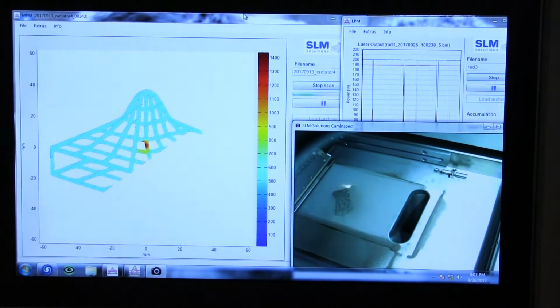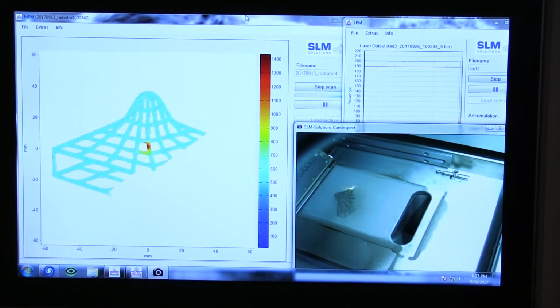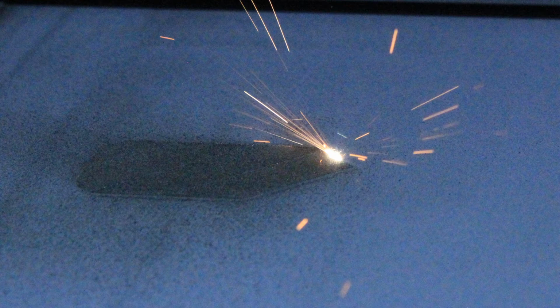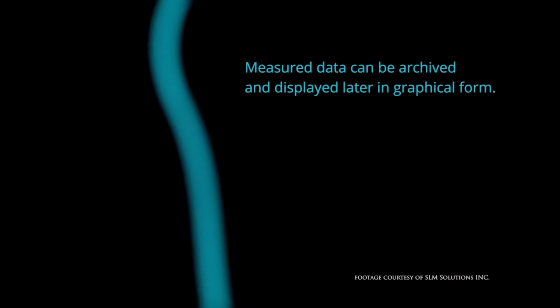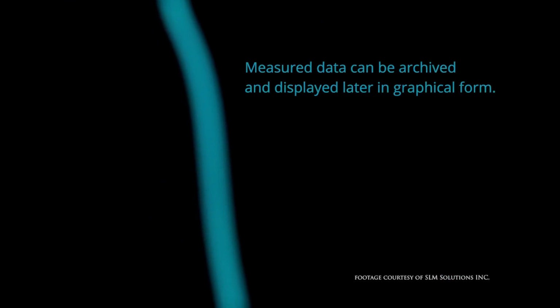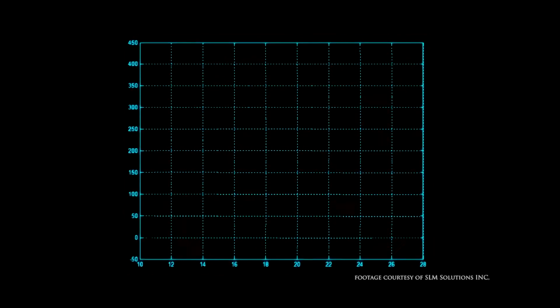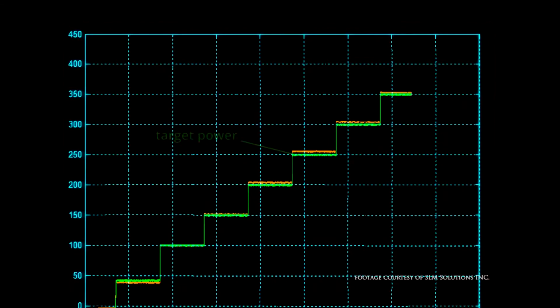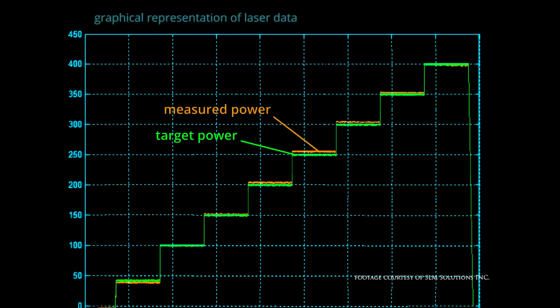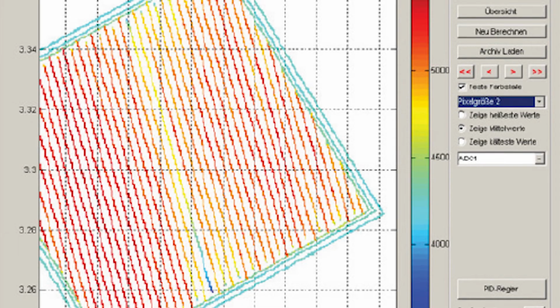So especially as you get into more and more different powders and some of the reactive powders like aluminum and titanium, being able to understand the thermal energies that are going on within the build becomes really important, especially post-build. Sometimes you might find certain surface roughness and porosity that is obviously an issue in part quality. And this gives folks a reference point to actually understand maybe what is happening critically inside the system to improve upon that or to create successful builds.